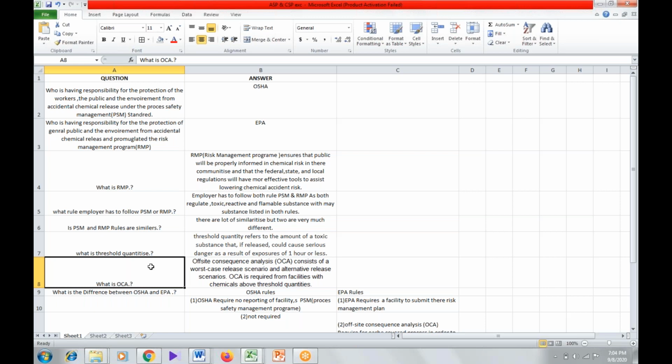Yes, you can. What is OCA? OCA, off-site consequence analysis, consists of a worst case release scenario and an alternative release scenario. OCA is required from any facility with chemicals above their threshold quantities.